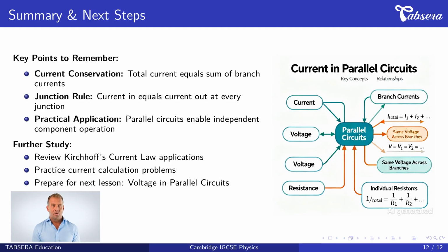Second, the junction rule, also known as Kirchhoff's current law. At every junction point where circuits branch or merge, the current flowing in must equal the current flowing out. This principle enables us to analyze complex circuit networks systematically.